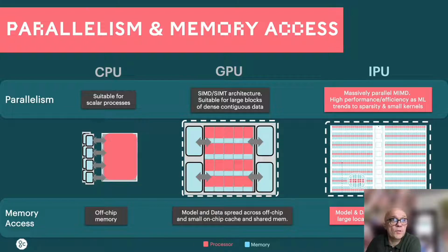Nevertheless, the IPU implements massive parallelism in a completely different fashion, using the MIMD architecture: multiple instruction, multiple data. And this is exactly what the machine learning workload wants. And this is also very good for sparsity in the small kernel.